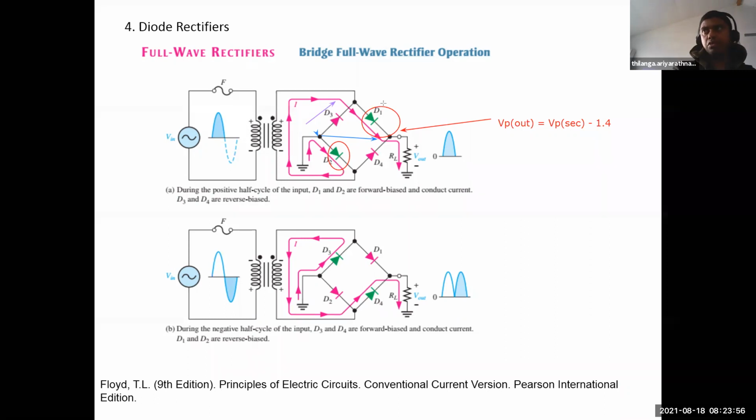Now guys, you can see we have a voltage drop across this diode as well. Okay, D1. When you add this D1 voltage difference to this one, then we should get the voltage across D3, or maybe not exactly voltage drop, the voltage difference between the two terminals of D3, because we only have these three elements, right? D3 and D1. We know the voltage between these two points.